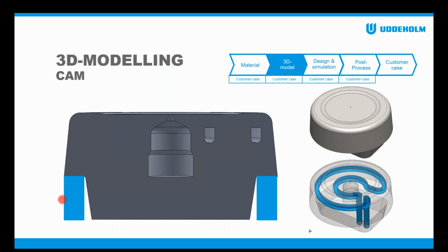Support material is the same steel grade that we're using to produce this part, but it's printed in another way, you could say. So we have some other parameters to print this material. But still, all surfaces that don't have any support underneath need to have support material. And this also goes for very tilted areas, like this one. Here the machine would also add support material, but also in the cooling channels. You can see these cooling channels are flat at the top. So here it would also add support material.